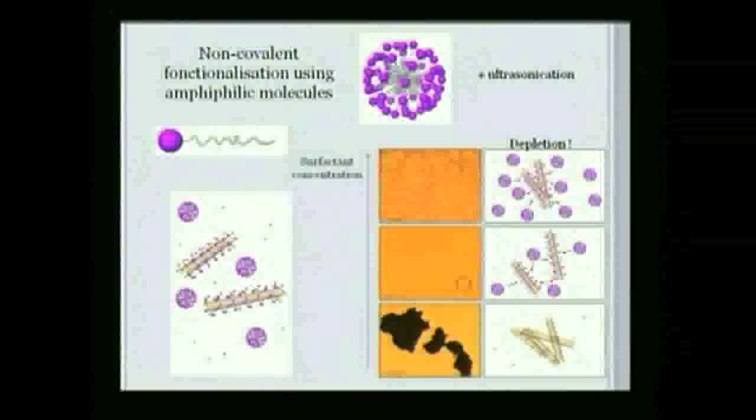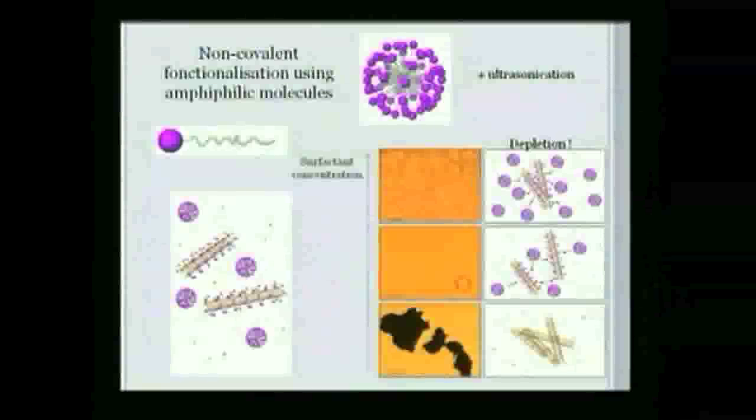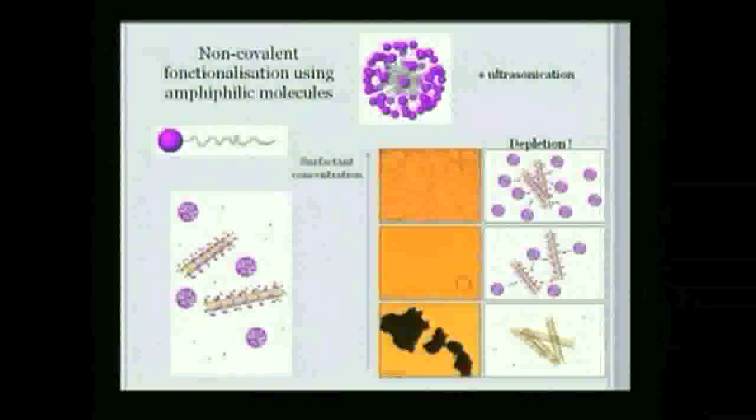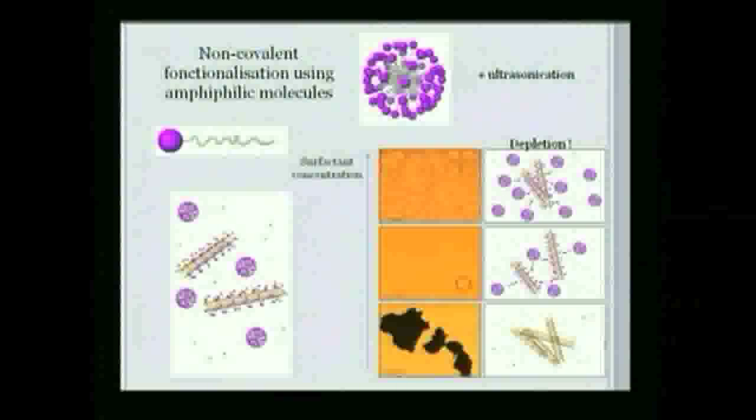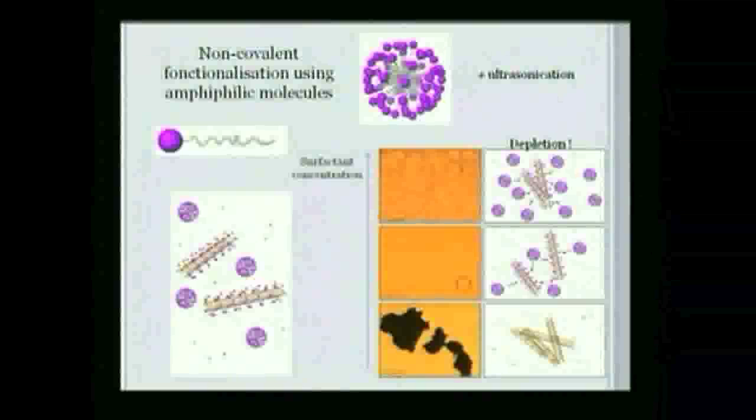Okay. So it's a very current method, and at the beginning, when people were using this method, they were thinking that in order to disperse the nanotubes well in the water, the best thing is to put a lot of surfactant. They said if you put a lot of surfactant, you are sure to disperse the nanotubes very well. It was not the case at all. In fact, there is an optimum concentration of surfactant to put in the solution, because it's very often SDS that we use.